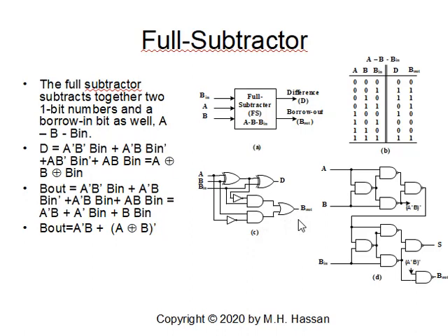And we can implement this also with nine two-input NAND gates, where I can get the difference D. This is not S, this is D. Okay, and this signal here, which is A prime, B prime, all prime, taken here. I didn't put the line to avoid confusion in the drawing. So this signal here, and this S has to be changed to D. This is the difference, D.